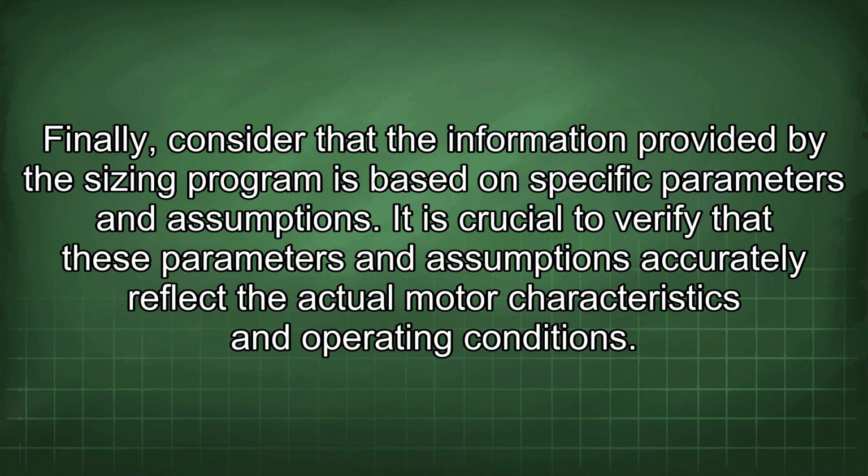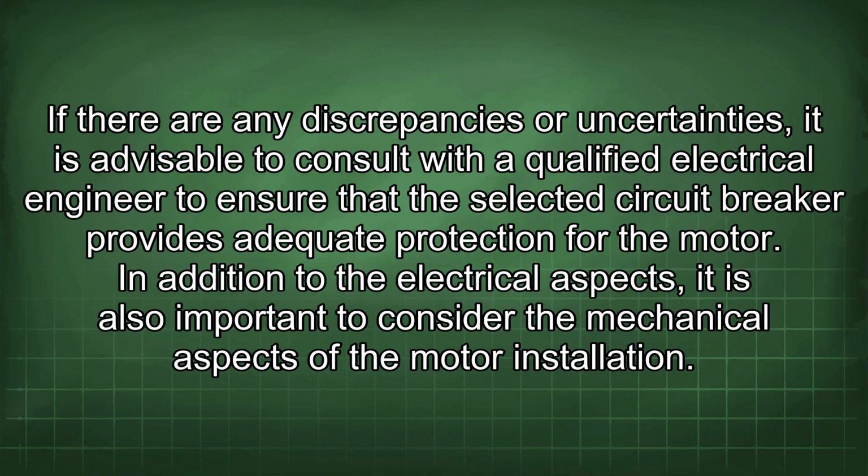Finally, consider that the information provided by the sizing program is based on specific parameters and assumptions. It is crucial to verify that these parameters and assumptions accurately reflect the actual motor characteristics and operating conditions. If there are any discrepancies or uncertainties, it is advisable to consult with a qualified electrical engineer to ensure that the selected circuit breaker provides adequate protection for the motor.